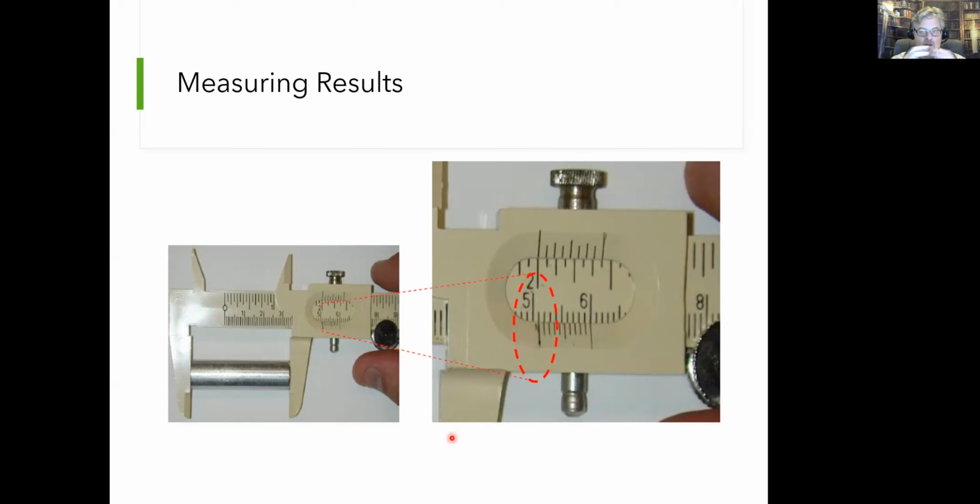So my problem was, when I was first doing this when I was 16 years old, I did not measure the parts. No one told me to measure the parts. I didn't know anything. I was a 16-year-old kid who just got thrown onto a machine, and I should have been measuring the parts on a regular basis. I should have been pulling out a part, measuring it, putting it back into this tray, and making sure that I was being very consistent in my cutoff.